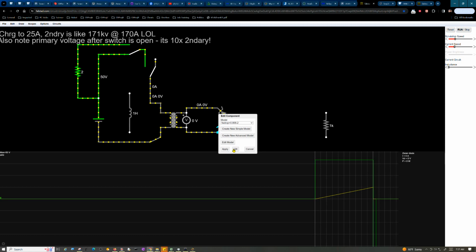It would probably take 1 amp of current on the primary if it was a 300 VA transformer, and if the secondary is rated at 10 amps, you're probably fine to try it. It's just, you may saturate your core sooner than you think, I don't know. I haven't investigated that enough, because I don't usually use transformers with DC signals, right? So I've never actually experimented with any of these on that level.